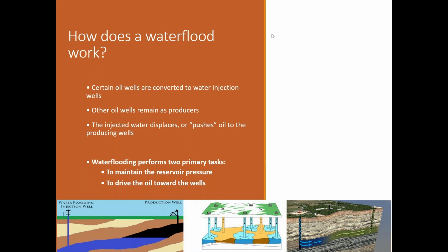Now we'll see how a water flood works. As I have told in the previous slides, some wells are converted to water injection wells, and I've already told that there is flexibility of conversion of production wells to injection wells in a bottom water drive reservoir, but that flexibility is not present in an edge water drive reservoir.